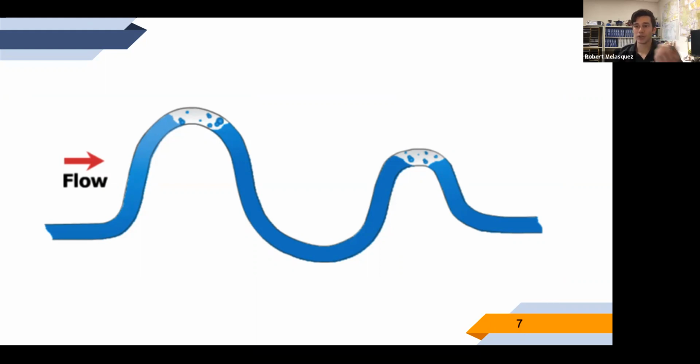When you get pipe and valves, they don't have water in them. They usually have air in them. And when you put it all together, it's all filled with air. And then you fill it, and most of that air gets pushed out of the end. That could be through the end of the pipe, or through hydrants or faucets, or when people use water. But air is lighter than water.